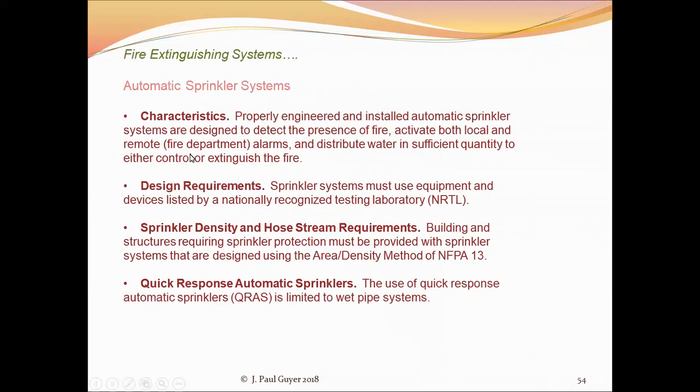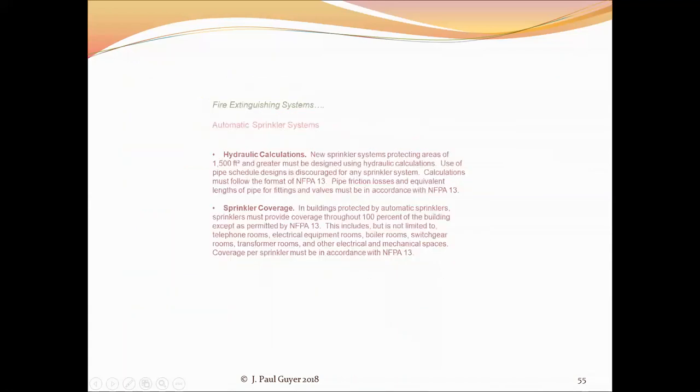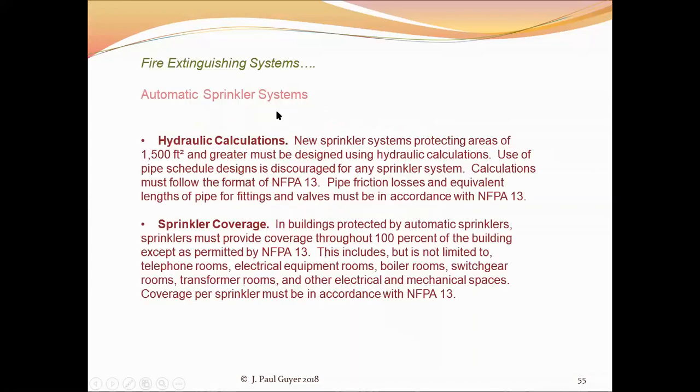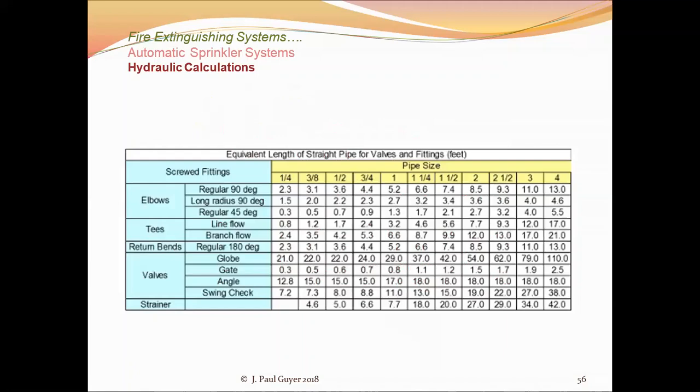Just a couple of minutes left. The automatic sprinkler system and sizing the pipes. And here's the way it goes. You've got water being delivered to your building from the local water utility at around 50 psi. So that's the pressure where the water enters the building.